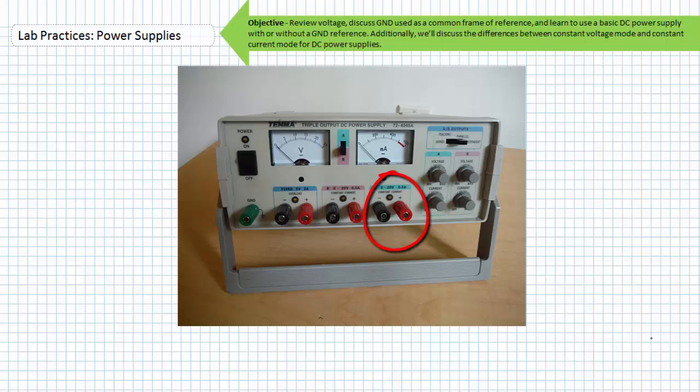There's an adjustable A pair, an adjustable B pair, and another fixed pair. All the way to the left is a single jack that serves as a ground reference. The 2 adjustable supplies go from 0 to 20 volts. Some versions of the same power supply go from 0 to 24 volts. The fixed pair always remains at 5 volts.